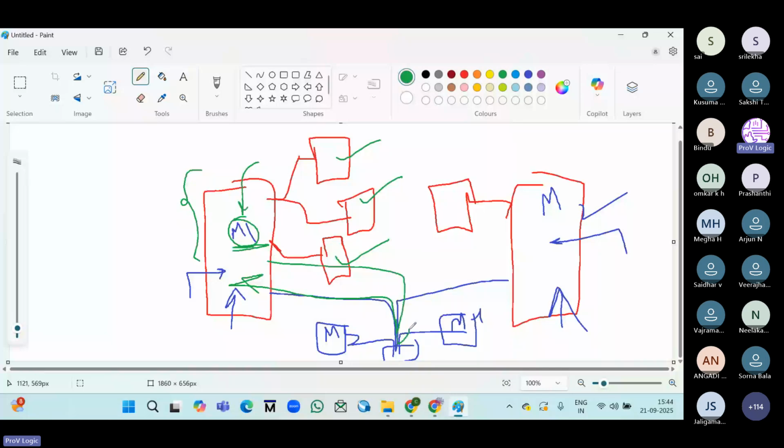the arbitration will be done now with these 3. Competition means which one should win the bus first, so that we know which one will do the task next. So now master 2 will win the bus, so master 2 will be activated, like microcontroller 2 will be activated. It does some drying or spinning of the washing machine. And microcontroller 3 will get the opportunity now to do its task, and it does some dry purpose or whatever. Okay, so this is exactly how the I2C protocol works between 2 different microcontrollers to transfer